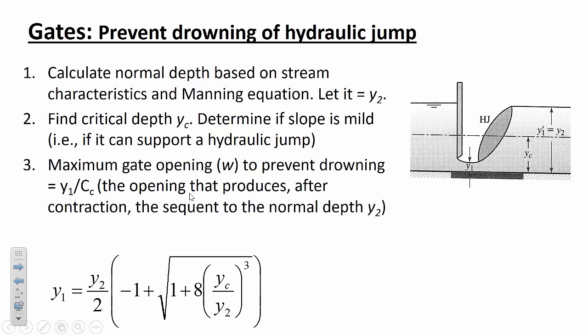So then you'd solve for Y1, where Y2 is the normal depth, and then once you know Y1 and the coefficient of contraction, you can calculate W.